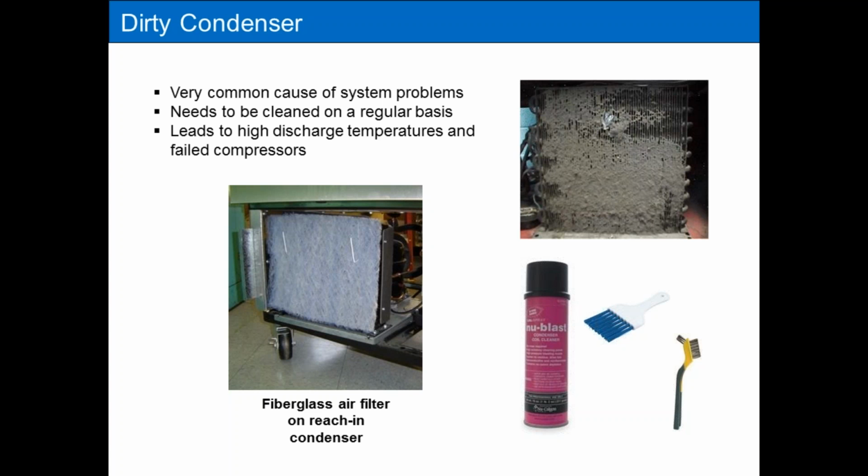Does it affect the airflow? Honestly, I don't know. I've used them. I've seen them on units I started doing maintenance on, where other companies had been using them in the past, and I've left them on, and I personally have not had problems with having them on. But I don't know that for a fact. If you know for a fact, or you have data showing they're good or not, maybe at the end of this presentation you can send us a comment about that. I've used them and not used them, but they're out there. Ice machine manufacturers use them all the time, so that's pretty common on ice machines, to have these filters on their condensers. But on reach-ins and coolers, I've seen them added on by techs.